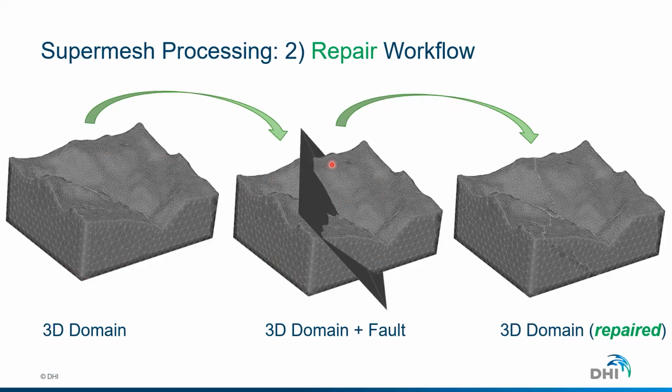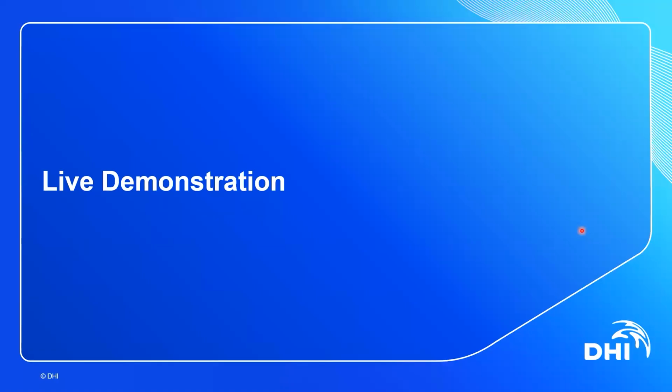So if you pass this to the mesh generator TetGen, it's not going to work. Using the Supermesh repair, you can basically throw out parts of the surfaces that are not necessary, and FEFLOW or GOD solutions will take care of the connection between the intersection of the plane and the topography and the outer faces of the box.